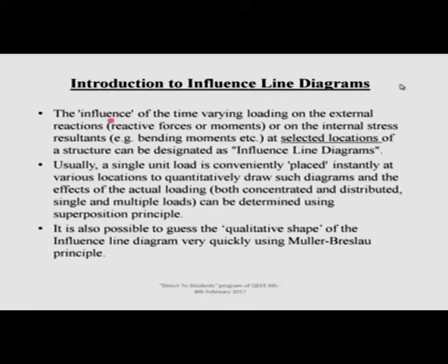The influence of the time varying loading on the external reactions, that is the reactive forces or moments, or on the internal stress resultants, that is the bending moments, etc., at selected locations of a structure can be designated as influence line diagram. Usually we are exploring what the effect of the loads is at critical locations.